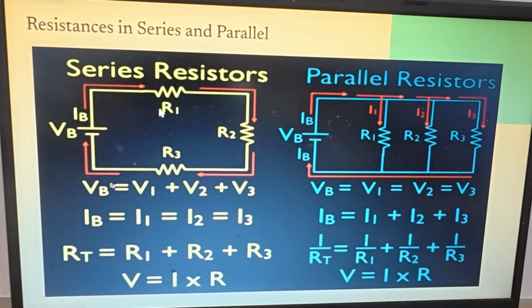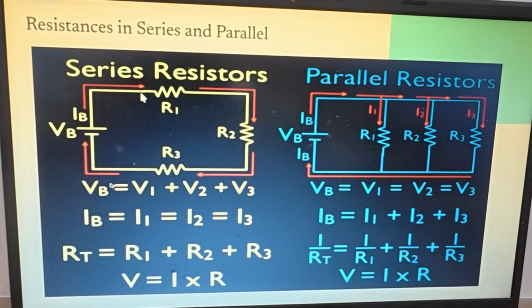And each resistor will have a voltage drop across it, and the sum of the voltage drops is going to sum up to V sub B, which is the battery voltage. So this is a direct current circuit. We're saying that the wires connecting these resistances to the battery have zero resistance, at least that's what we're defining. In reality, there's some resistance there, but we're not bookkeeping it.